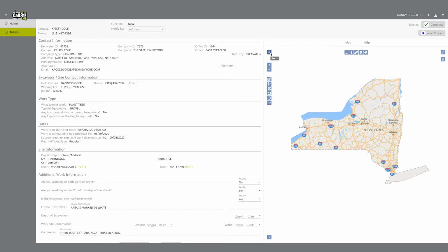The magnifying glass in the top left corner is your search tool. You can use the search tool to look for streets, places, points of interest, latitude, longitude, coordinates, statewide, or within your current map view. To utilize the search tool, click on the magnifying glass. You will notice that the icon will turn green and you will see a drop-down arrow in the left-hand corner of the search field. To view your options, click on the arrow.